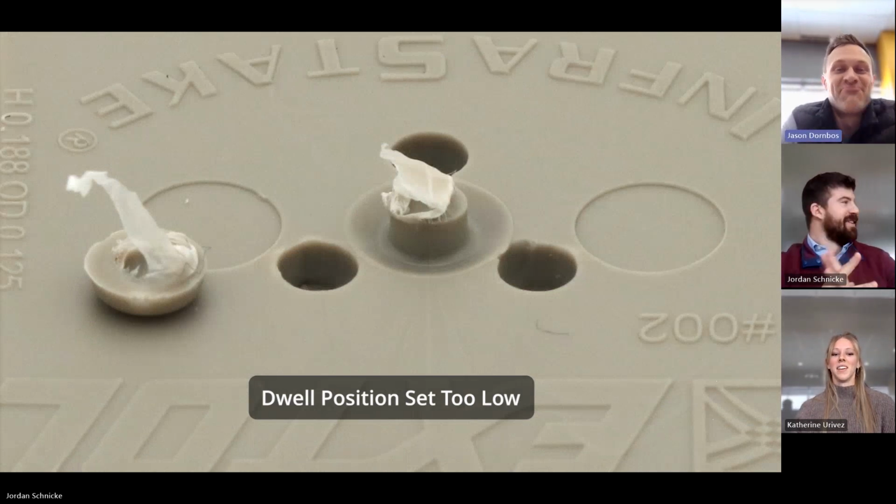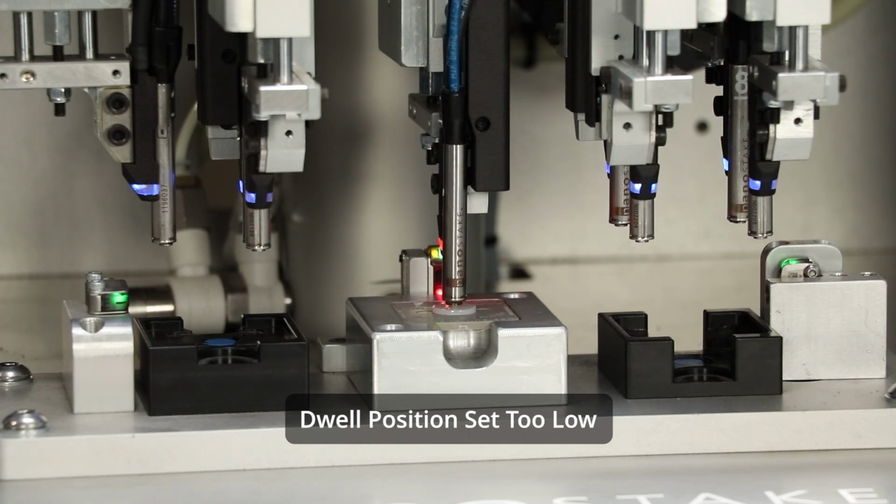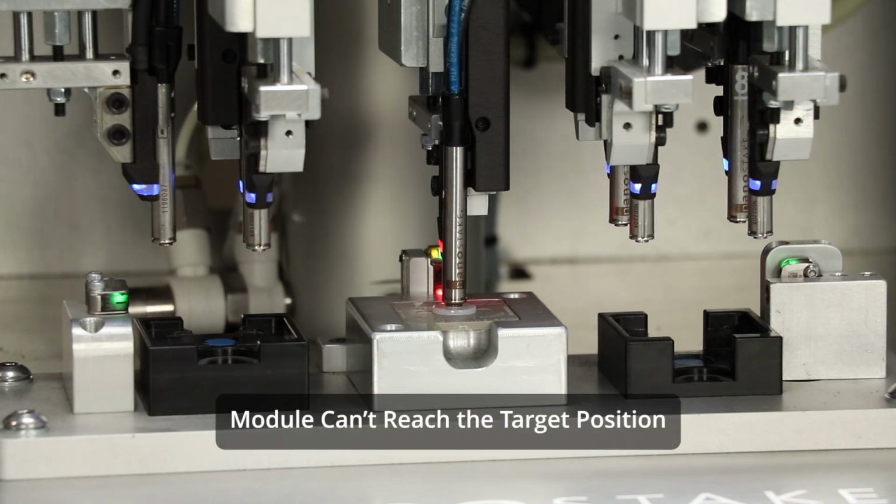So this video is your dwell position is set too low. That module is trying to reach a position that is too low. It can't get to it because that mating component is keeping it from reaching the position you set. So it just sits there, and sits there, and sits there.